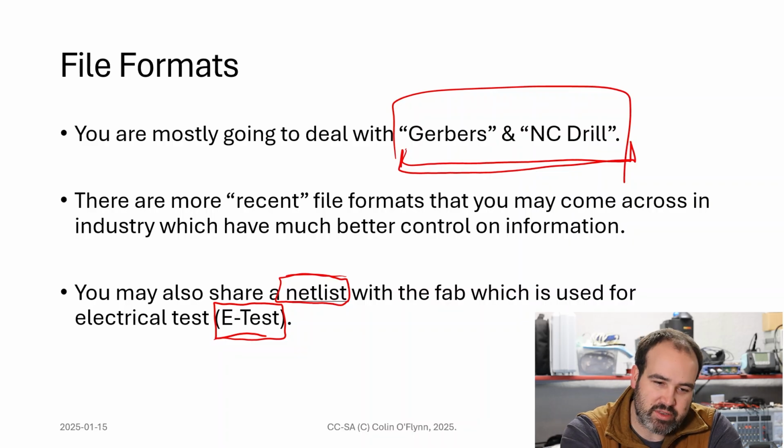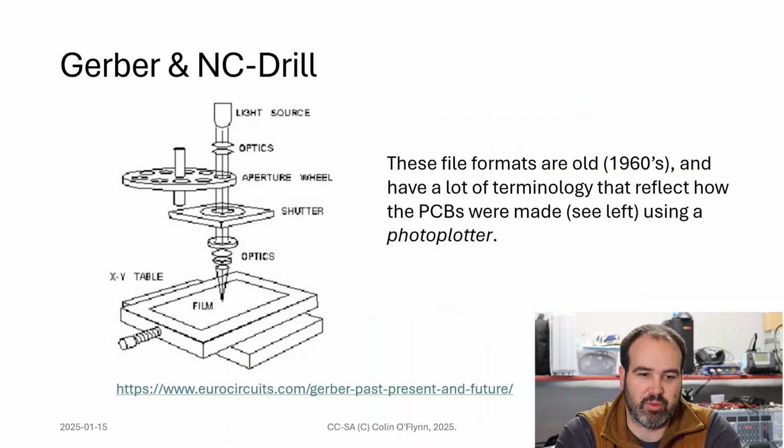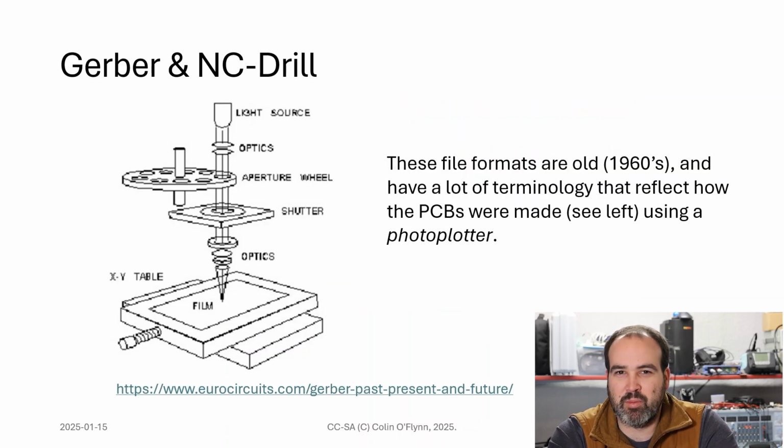But the thing is, if you don't do this, you could build up a board, and the board has an error from the manufacturing, not from the design, right? And that can be really hard to troubleshoot if you have a new design that you don't know if it works or not. So it's something I encourage you to do. The cost is pretty minimal normally, unless it's a really simple board that you can look at. But once you get to multiple layers, it's always worth doing e-tests.